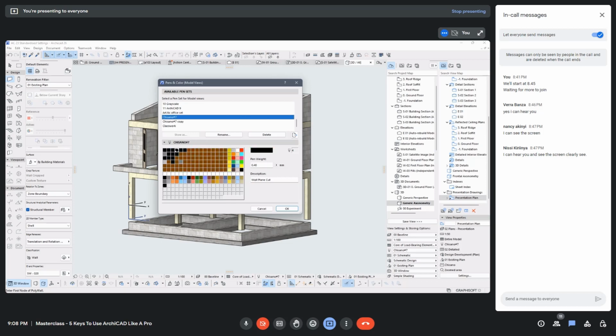I think of pens or how they should work as drawing pens. If I'm working with outline drawing pens, I know they are from 0.1 to 0.8 or 0.03 to 0.8. So these were the first pen set I created for myself. This was back in 2020. So right now it's evolved to the point that now my pens are linked to scale, in that at different scales that pen weight continues to change.